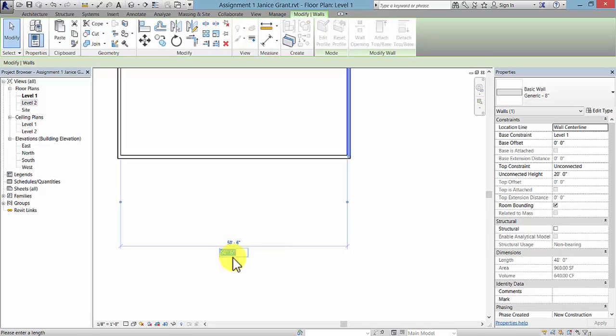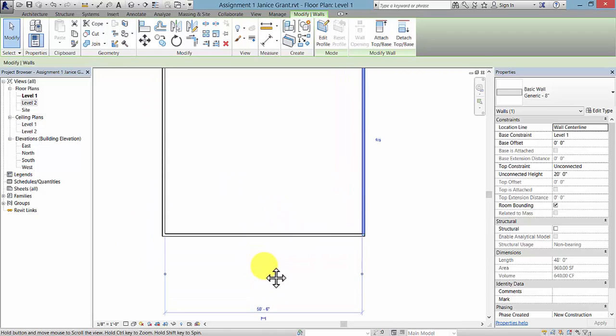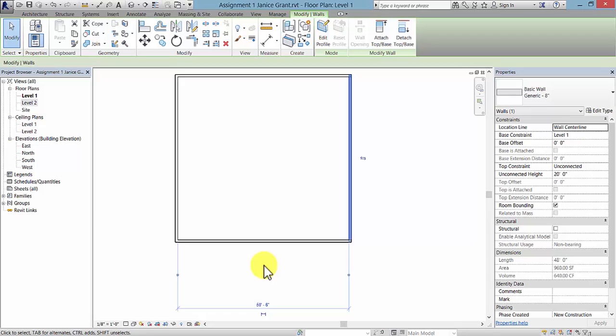If you only had inches, then you would have to force the inches in with the quotation marks next to the enter key. It would be a shift here, quotation marks next to the enter key on the keyboard. So go ahead and use whatever number you'd like, because you will be creating your own floor plan based on the tools that we're learning.